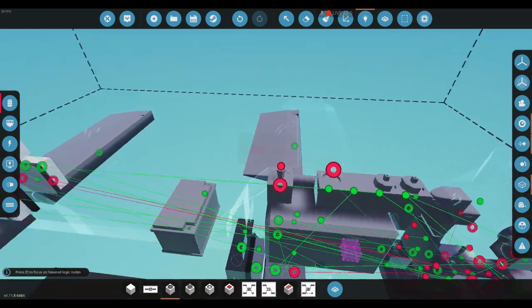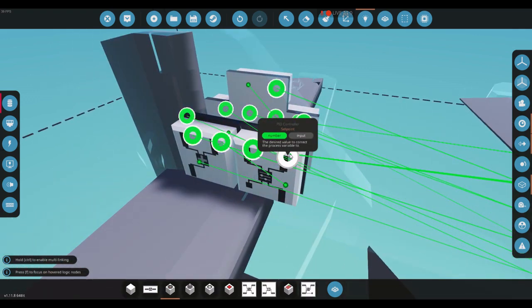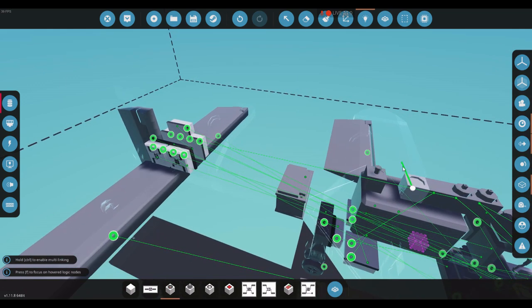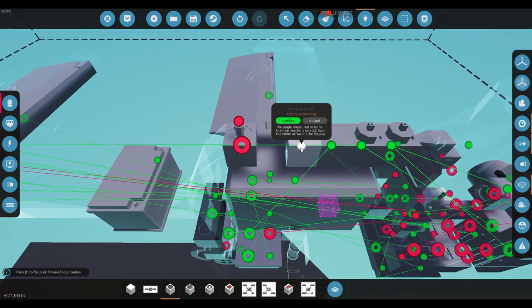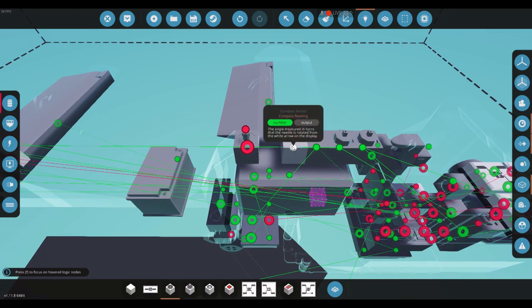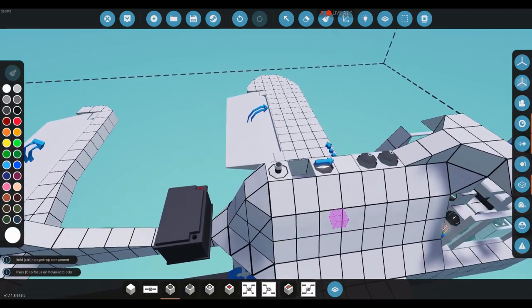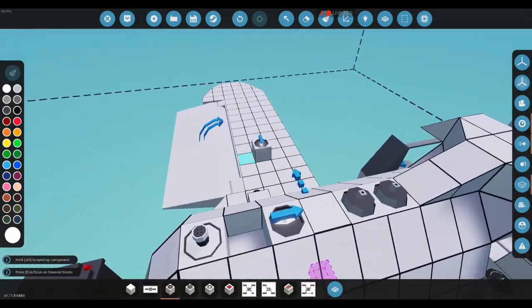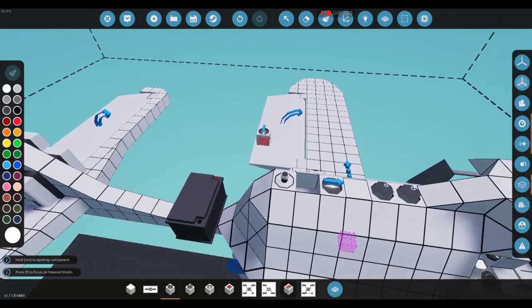Now, unfortunately, you would think by this point that we would put the compass reading directly into our PID's process variable if we want to do a compass heading hold system. Unfortunately, the game is not this simple, and the compass sensor only displays a value between -1 and +1. For a compass to function properly, you need a value anywhere between 0 and 360, and these will represent your compass heading degrees. For example, 90 degrees is east, 180 degrees is south, and so on.